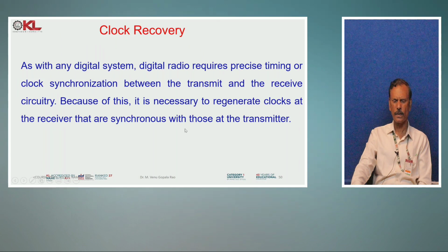The next is clock recovery. As with any digital system, the digital radio requires timing or clock synchronization between the transmit and receive signal circuitry. Because of this, it is necessary to regenerate clocks at the receive side that are synchronous with those at the transmitter.